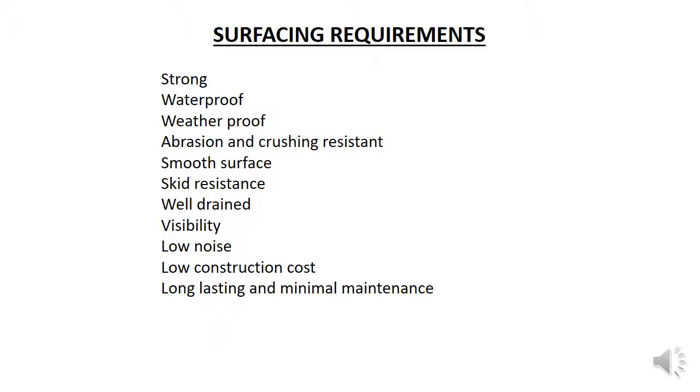There are a variety of requirements for the road surface. The surface has to be strong enough to resist the loadings from the road. It needs to be able to transfer the wheel loads down to the base course without cracking or breaking up. It also needs to be able to transfer the shear forces caused by turning, braking, and acceleration to the base course without unraveling. This means there needs to be good adhesion between the surfacing and the base course layer.